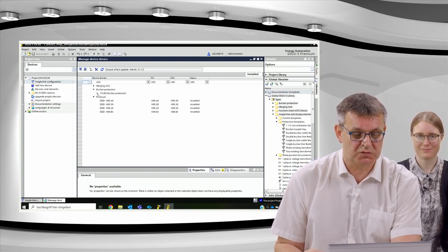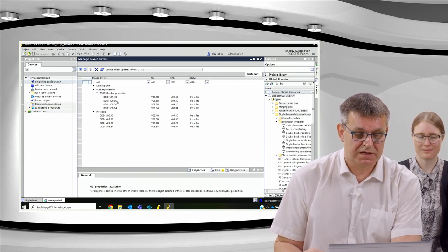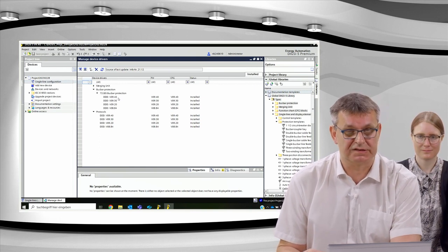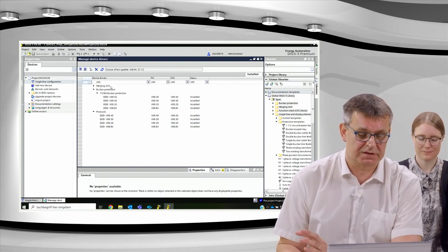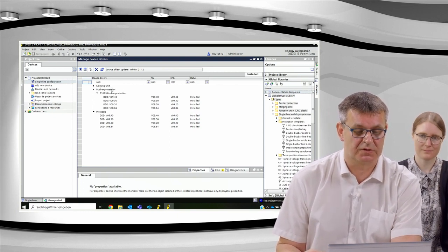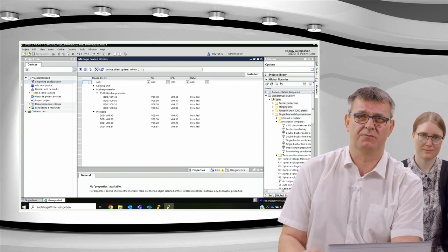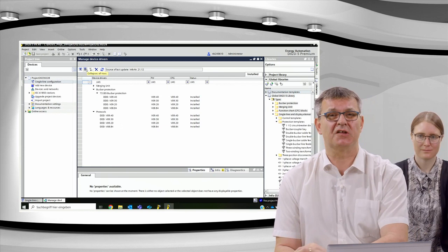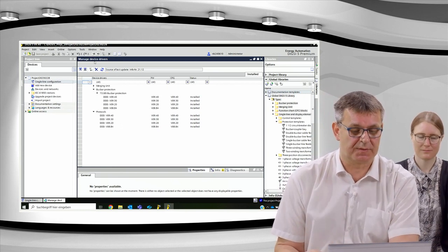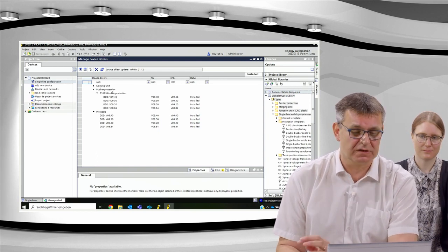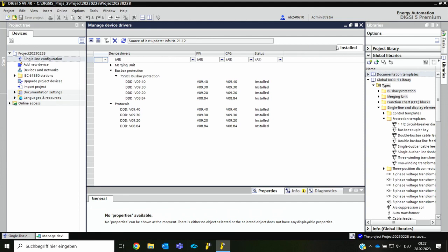And for busbar protection we have the 7SS85. We have versions from 8.84 until version 9.40. 9.40 is the newest one, and I will create for our demonstration, of course, the newest firmware version, the 9.40. And what again is very important to see is that we have one device which is able to make a centralized busbar protection, a distributed busbar protection, and it's only one firmware, one code, one device where you can configure really all different types of busbar protection. Okay,